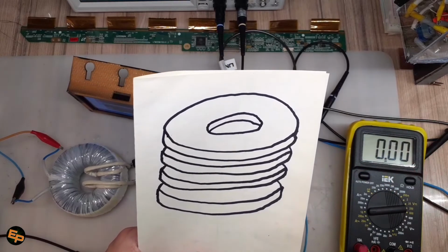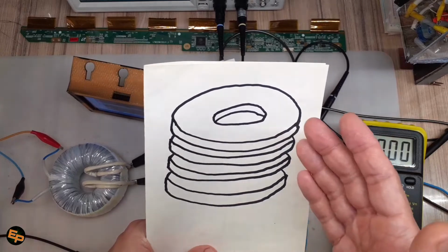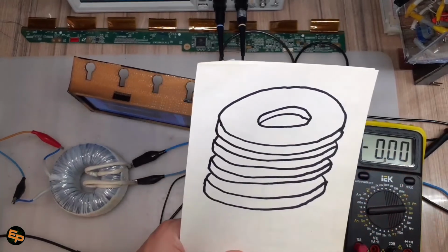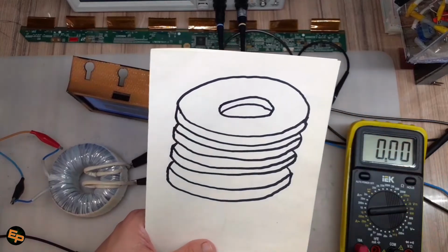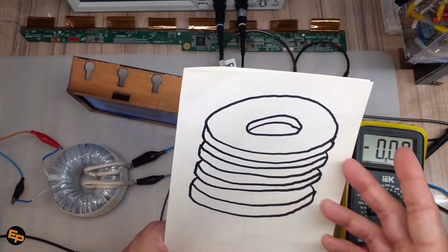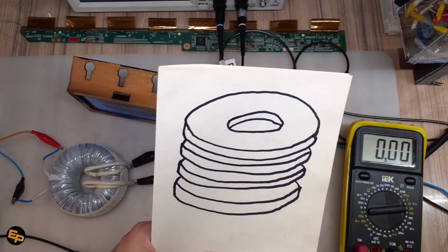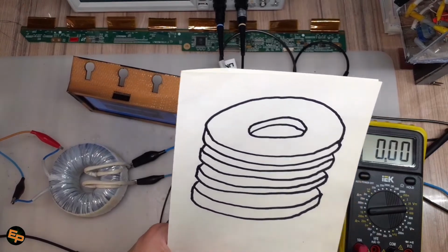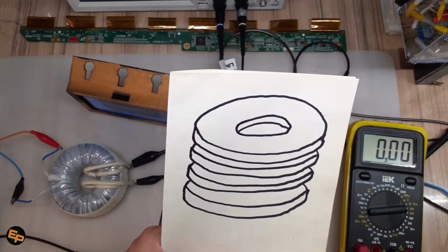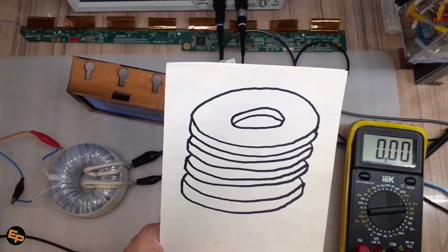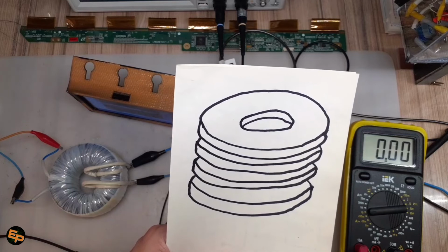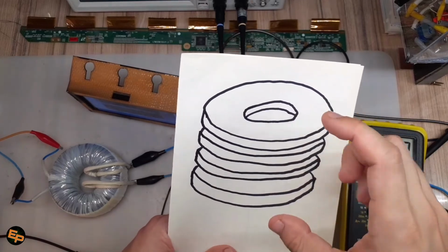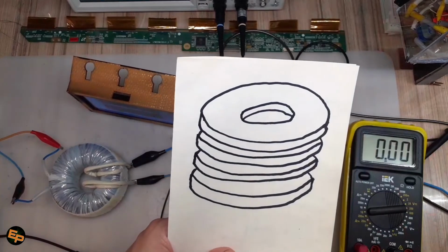The idea is that, of course, it could have worked with fewer turns, but you don't want to have too few, because the voltage then, especially at small currents, will be very, very small, and it will be difficult to work with. I would say that 100 turns is the minimum. And I will show you shortly what voltage it gives for various currents.